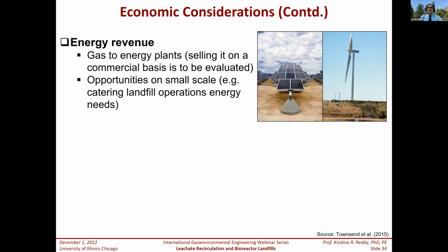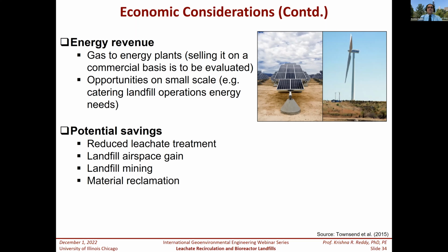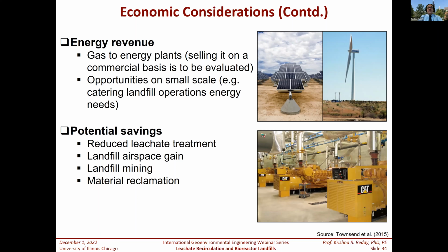Whereas in bioreactor landfills, because you're accelerating the waste degradation, you're going to get a substantial and reliable amount of gas generated, so you can have gas-to-energy plants, and you can have some recovery of expenses from the energy that you sell out of these plants. And then you have a lot of savings, right? You have leachate treatment, you're not doing that, and landfill airspace gain.